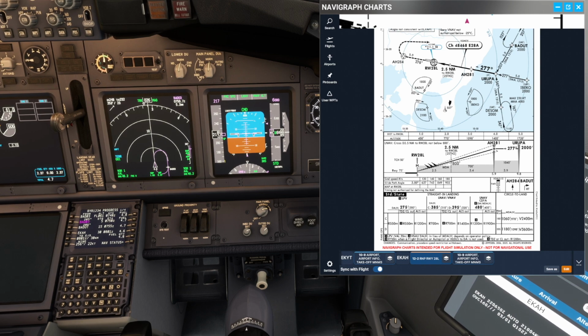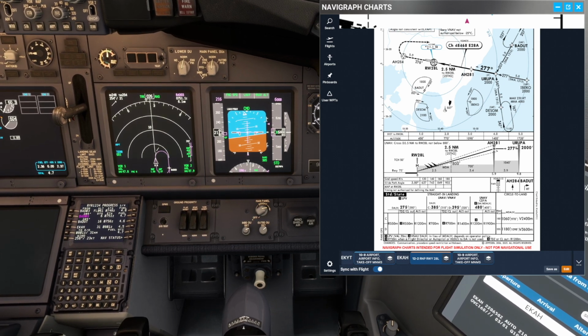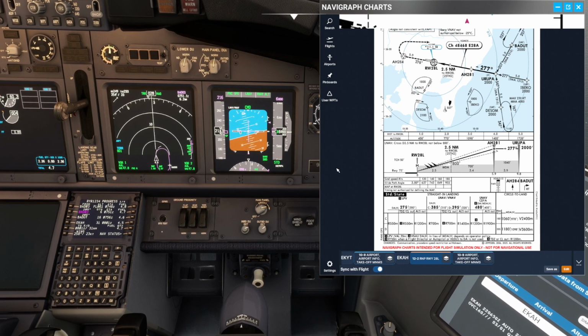Nine out of ten times, you know, because we do have false glide slopes as well. That's a different story, but QNH blunder error is because the glide path of this is calculated according to the GPS distance to the runway and the altitude you have set with reference to your barometrics. This means that this runway point right here can be changed. If we have the incorrect QNH set, we will end up high or low.